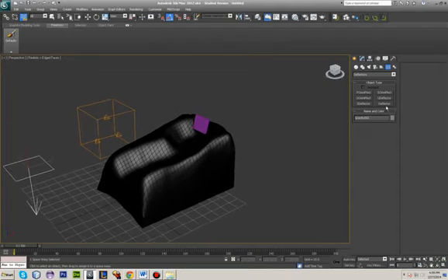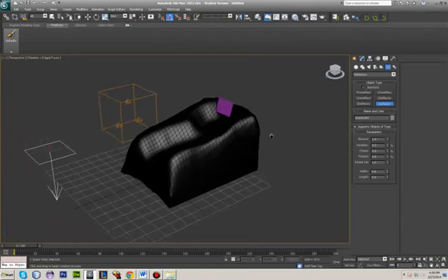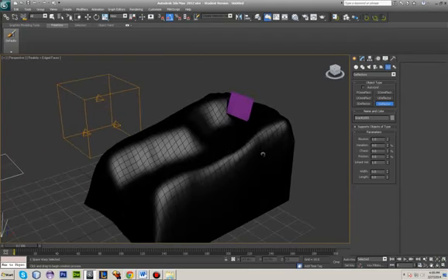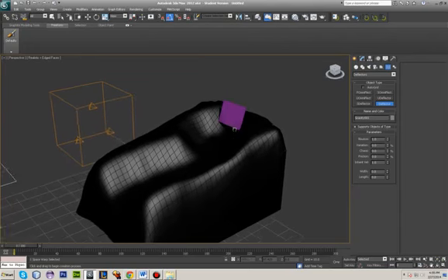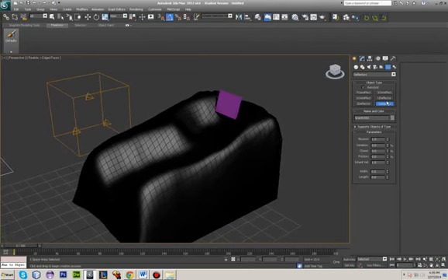And then there's also a deflector, where you can draw a plane. It will not be rendered, and it will serve as an invisible barrier, so that the particles will stop when they hit it and perhaps rebound depending on what parameters you set. As you can see, all the deflectors have different options here, and the one we will be interested in changing is bounce.